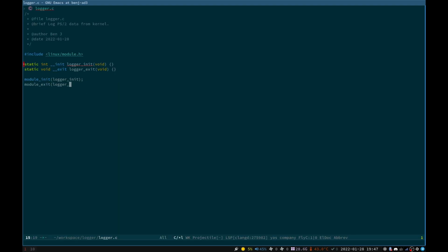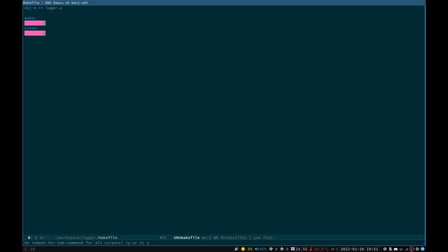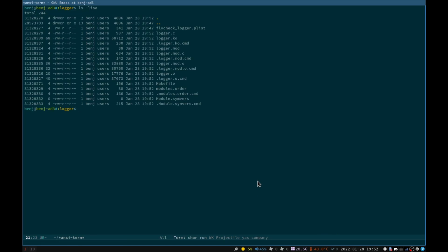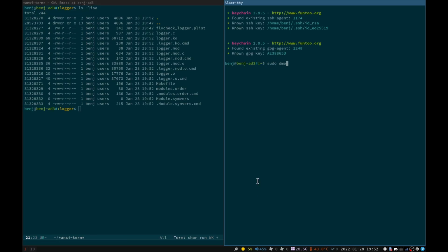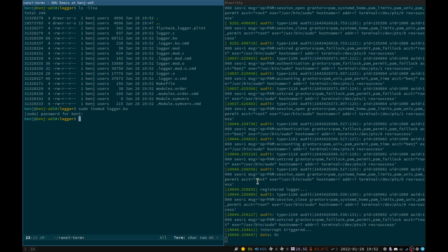Now that we know what protocol our keyboard is using to communicate, we write our kernel module, intercept those calls, and then we're going to print them directly to the ring buffer. After loading our kernel module, we see that when we press the A key, we output all the data to the ring buffer, which is exactly what we expect with the PS2 protocol data.